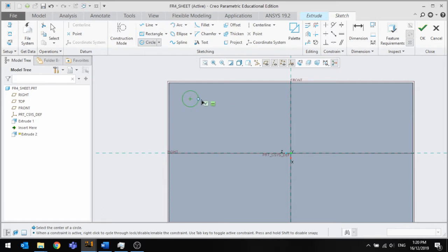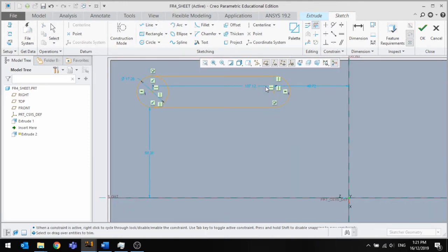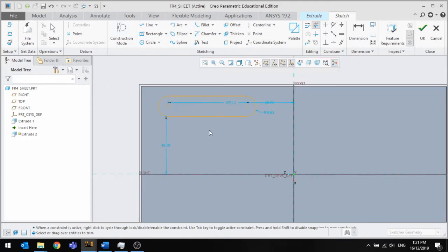There's a little dotted line here that it shows to make sure it lines up properly. And I'm going to snap it to the same size there. Middle click to finish. Line tool, the one that you never use. From there to there, middle click, here to here, middle click again. I'm now going to get delete segment out, delete you.